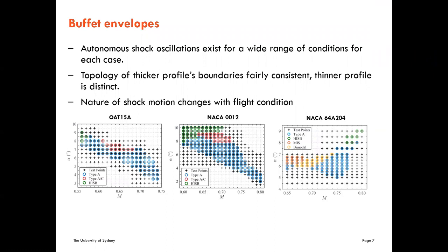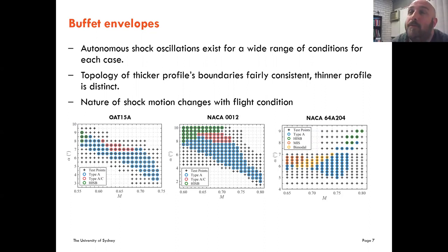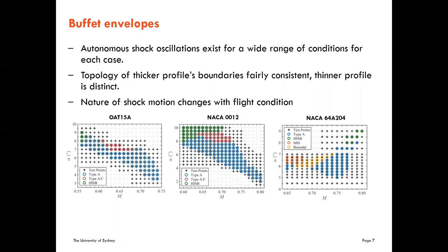And the final question I have is, how did you apply DMD for the linear stability analysis? Like in the Gao 2017 JFM paper I once found, they applied some kind of ERA, eigensystem realization algorithm. So they produced a linear system for the aeroelasticity, and from that linear system they determined which modes actually go unstable, and from that they computed whether it is resonance or actually buffet.